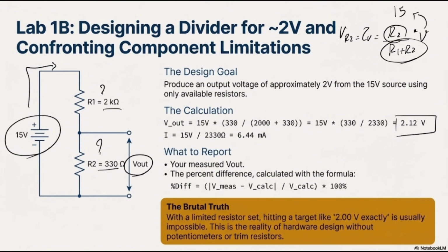At this point we use another equation. That was the first equation, and for instance the question says that the current that goes through your circuit shouldn't be bigger than 10 milliamp. So we would say that V divided by R1 plus R2 should be less than 10 milliamp.